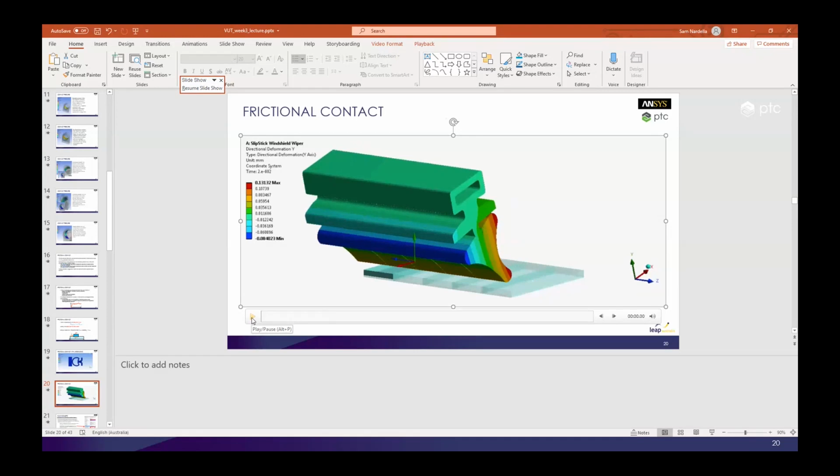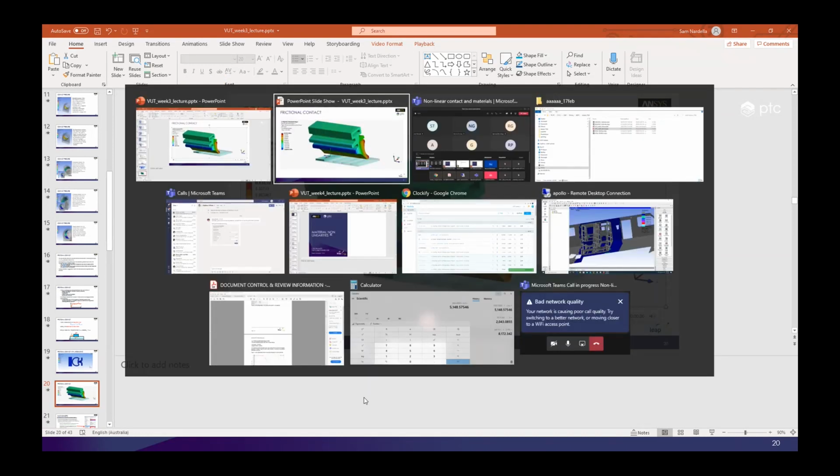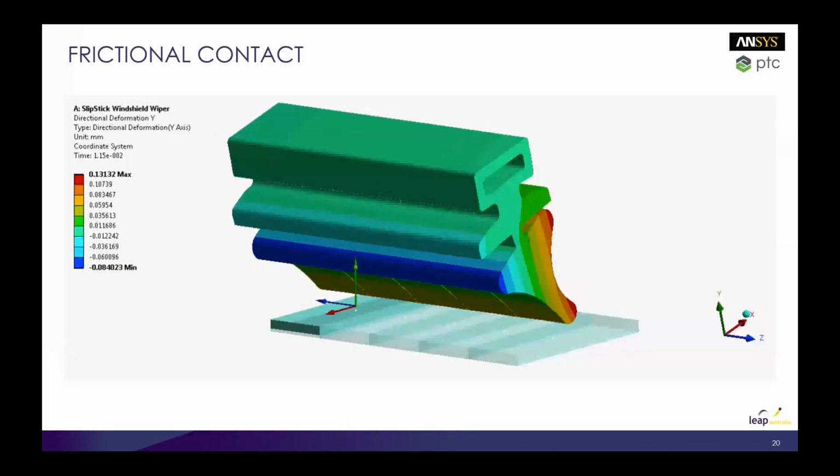If you put a little bit of soap in the windshield washer bottle, it acts as a lubricant. There are also treatments you can put on the glass, although they will wear off very quickly. Or when you put on new wiper blades, there are still oils from the manufacturing process of the rubber, so they also act as a lubricant.